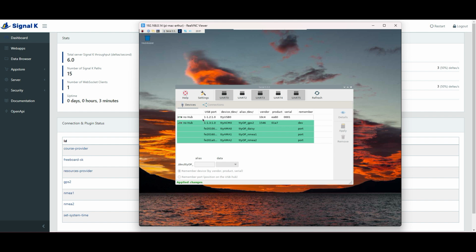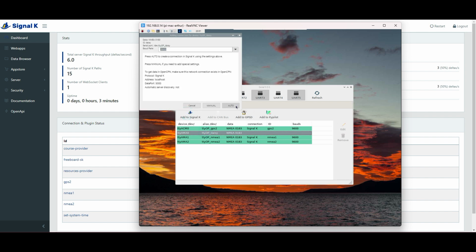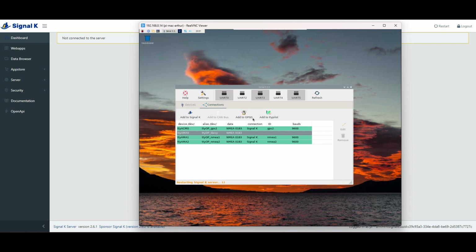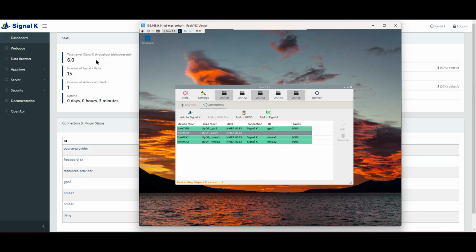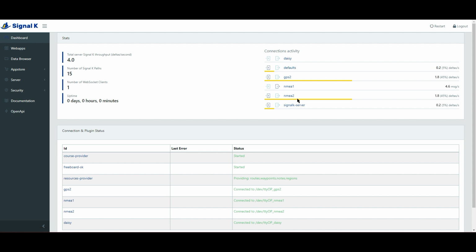And we have our device virtualized here as a dAISy, and now we just need to add it to Signal K. And you see that the server in the background is restarting, so the Signal K server is open here on my web browser, and it is restarting. And after restart, you can see that on the dashboard we got the dAISy here on top as an additional device. Okay, so this is the dashboard in Signal K, and it's really nice that you can see input and